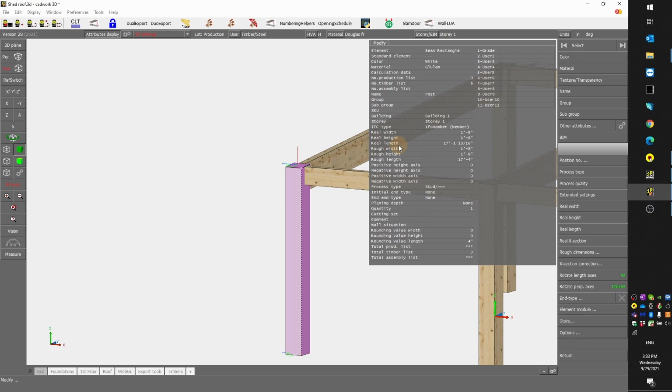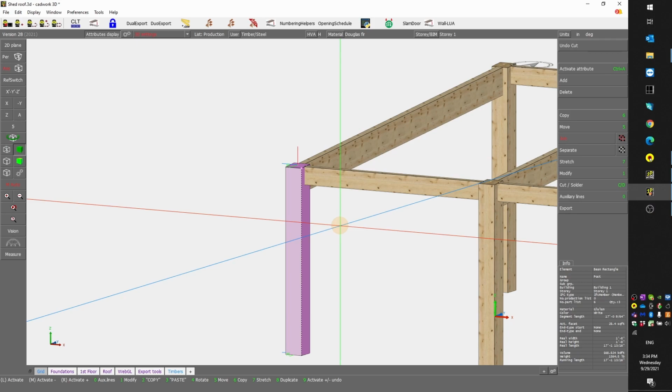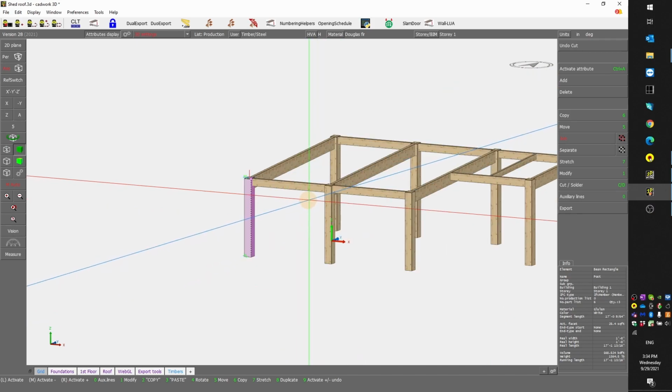But when you make a list, when you compute the board footage, it's based on the rough dimensions, and you will be ordering probably a 10 feet, a 10 footer or 16 footer. So that has to be rounded as well to order the proper length.